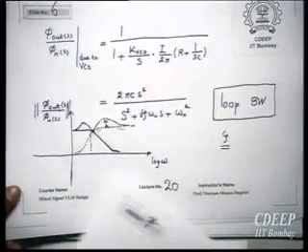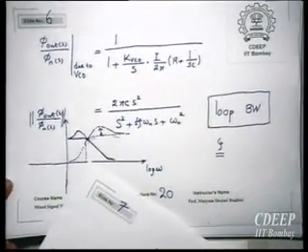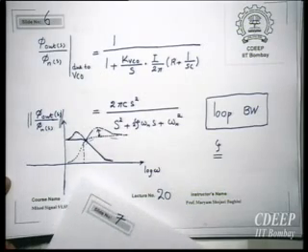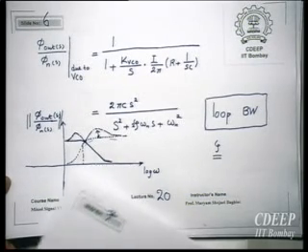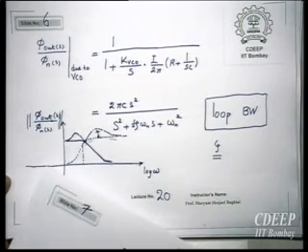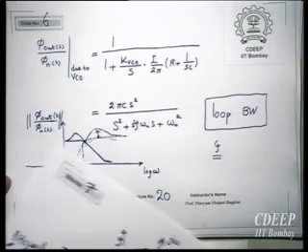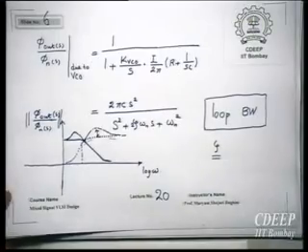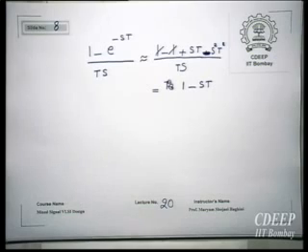So effectively, what does it mean? It means that if I want to choose the bandwidth of this filter, because with respect to VCO jitter it is a high pass transfer function, I have to choose the bandwidth of this filter properly. At the same time, for input jitter and for locking performance, I want to choose a low bandwidth. Therefore, there is an optimization. Okay, so this was some of the non-idealities in the PLL loop.